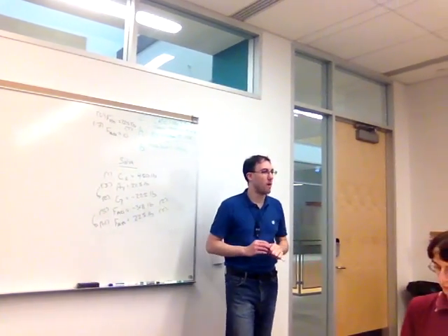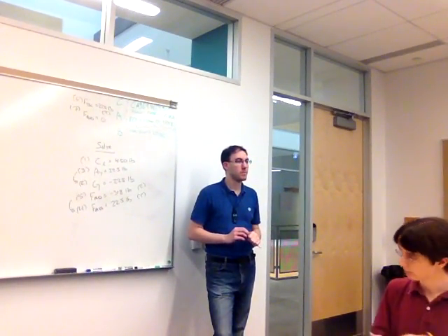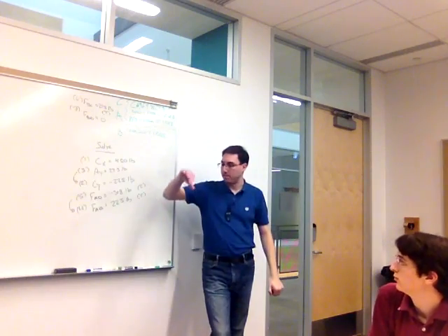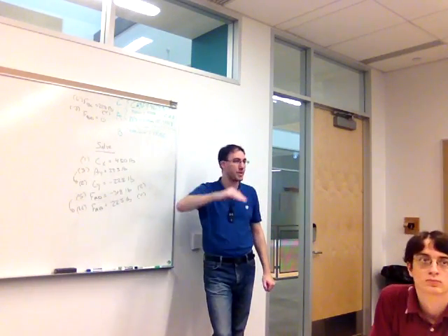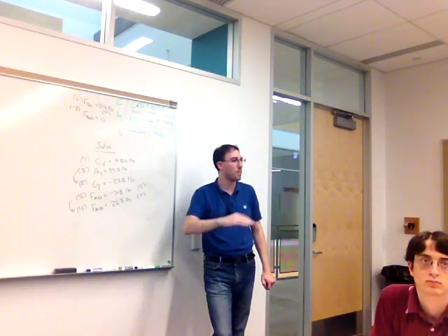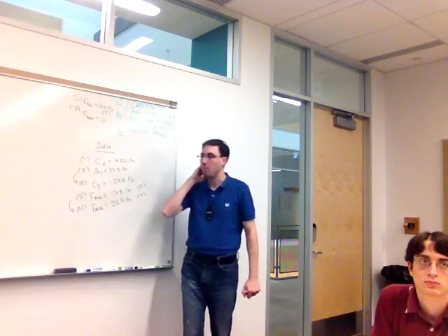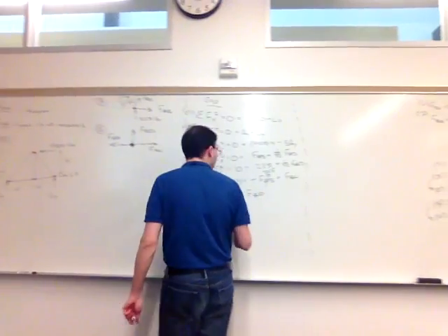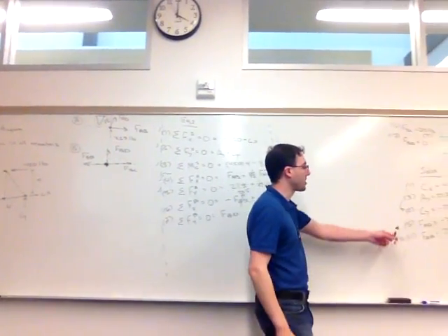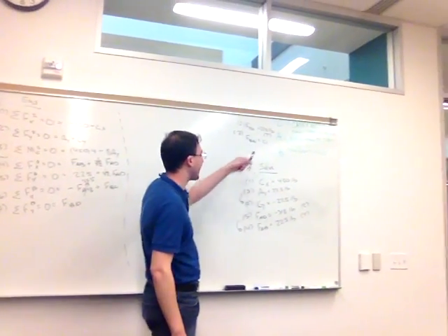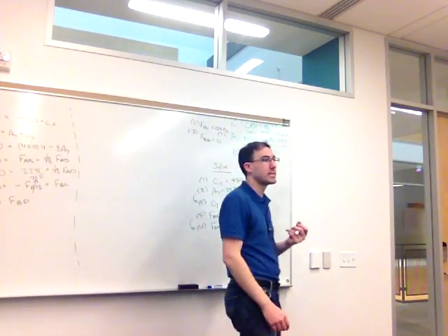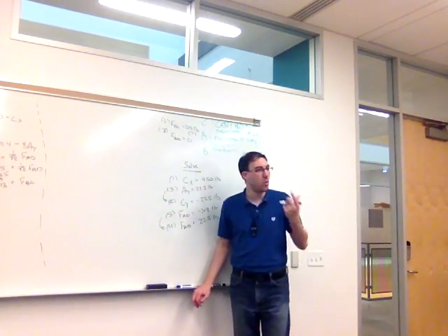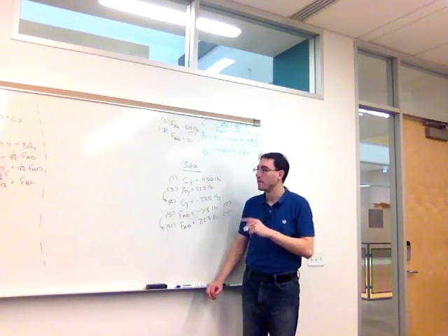All right, questions so far? All right, so again, I draw a free body diagram, I write the equations from it. Once it's used up, I march along to the next point that, by hand at least, is going to be the easiest. We have 4 of our members solved for: AD, AB, BC, BD. The only thing we don't know is CD at this point, so there's only one unknown left in our problem.